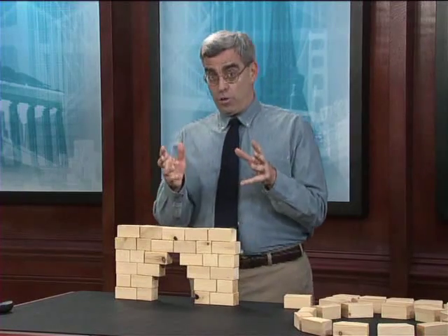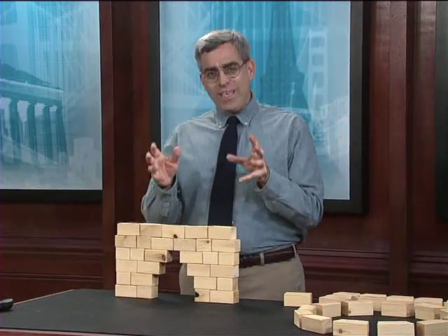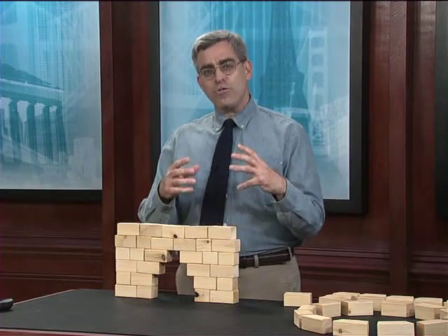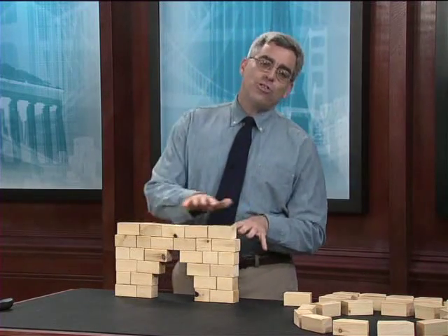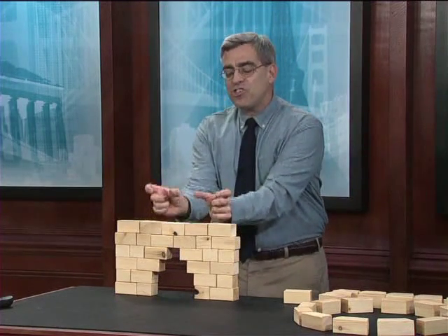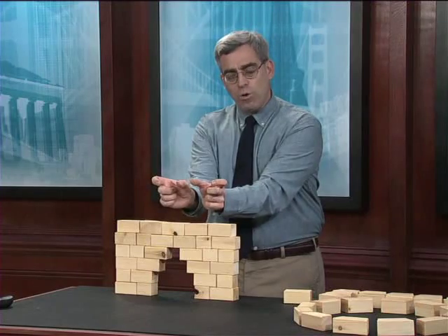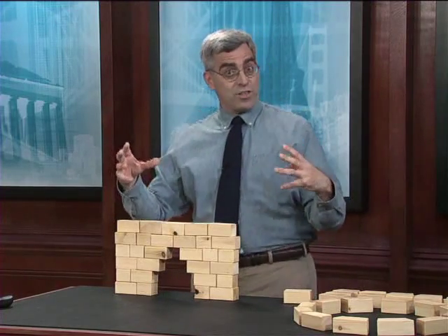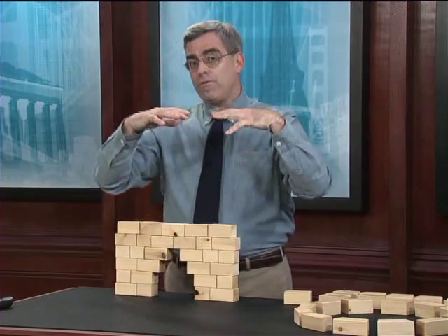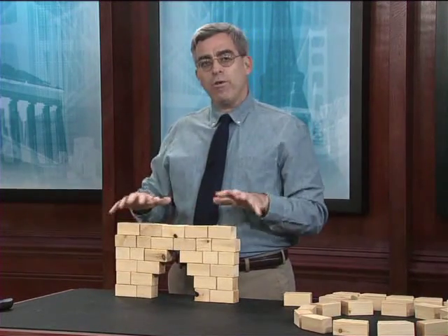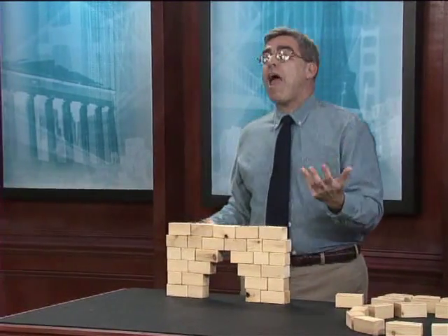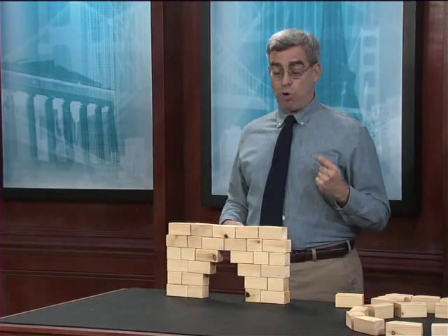The other thing I'd like you to notice about the corbelled arch is that it only actually works if each projecting stone is further stabilized by an additional layer of stone above it. If all we had done is provide this single series of stones projecting inward without those stabilizing layers above, the entire construction eventually would have fallen in on itself. We need that outer stone out here in order to keep it stable. We'll see that same general characteristic when we talk about the corbelled dome.